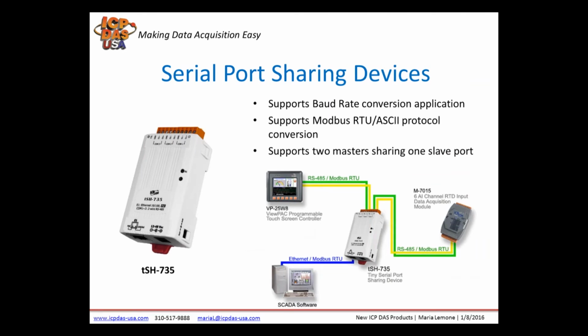The TSH-735 module is a serial port sharer that provides a number of functions including baud rate conversion, Modbus RTU ASCII conversion, and 2 masters share 1 slave. It has a built-in web server for configuration.